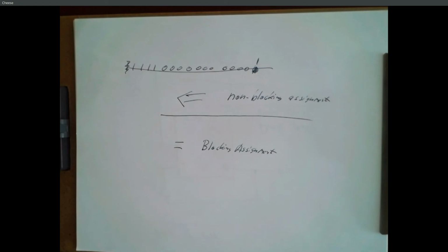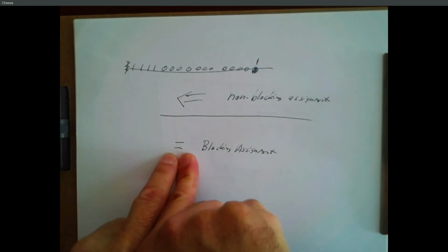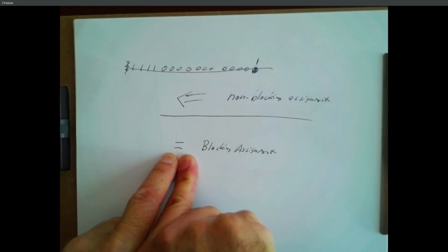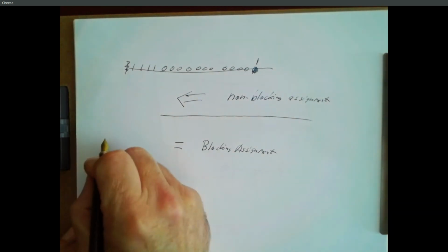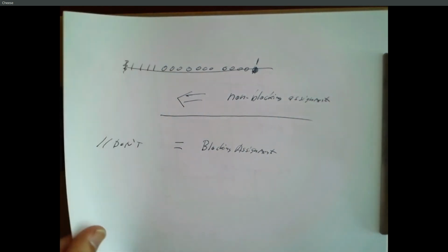And we don't usually want a blocking assignment, because we're forcing our parallel hardware to act like it's sequential. Anything that comes after this will not happen until this assignment has taken place. So it's acting more like code. So don't do that. So let me show you the effect of this on synthesis.